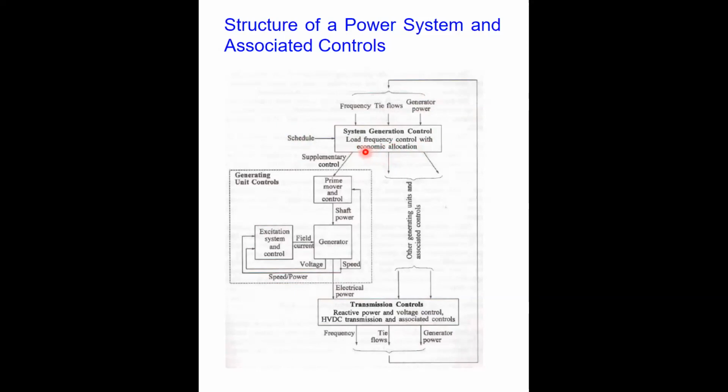And so as you can see, at each generating unit level, there is a control action through the governor for speed, for frequency, you can say. Then the several generators and the power plants in our network are interconnected, because this information is also shared with other generating units.